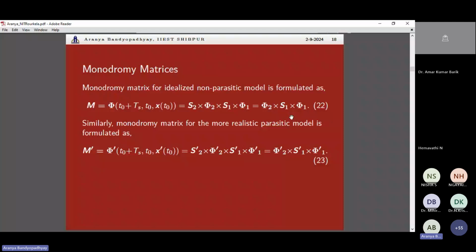When you are dealing with state space average modeling, or some linear paradigm of stability analysis, you try to keep the poles and zeros in the left half. You are analyzing stability in the S plane, but in this case it is in the Z plane. So, when the eigenvalues are within the unit circle in the Z plane, it indicates a stable system. And when even one eigenvalue is outside the unit circle, it indicates an unstable system.